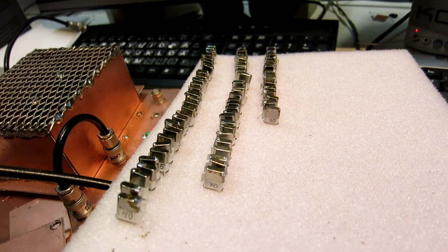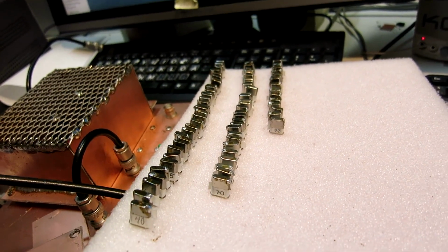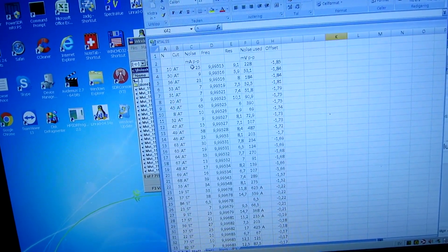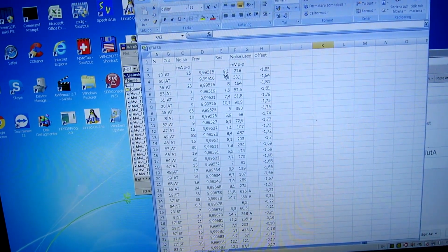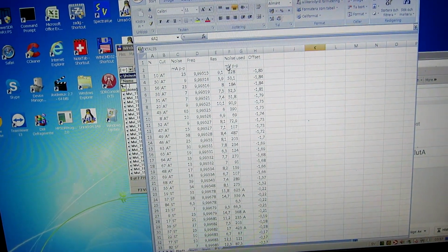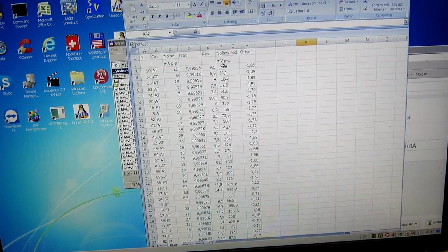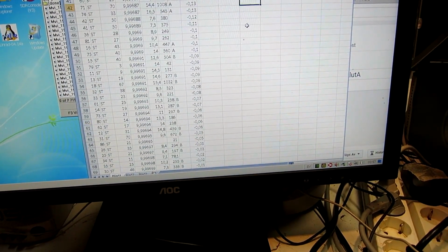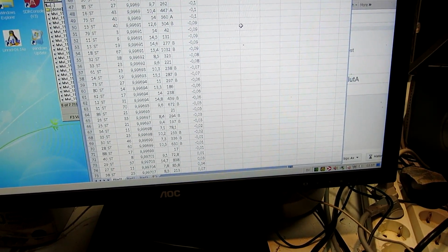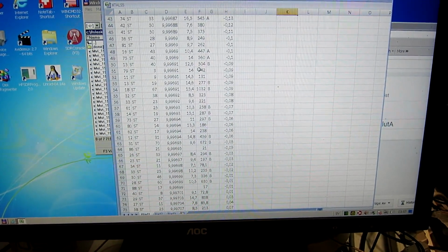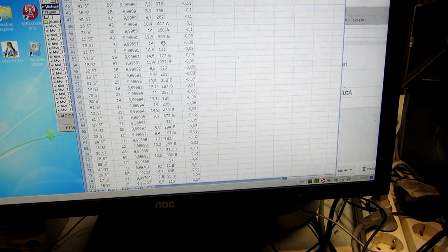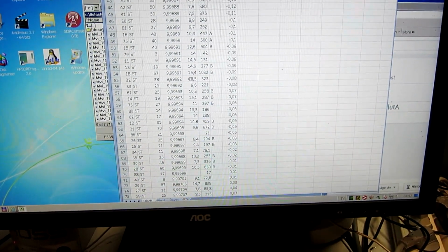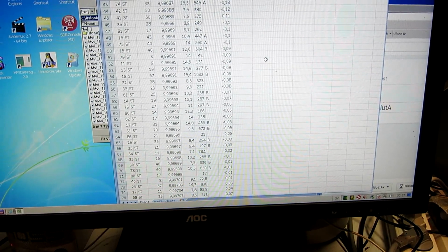These are all my 10 MHz crystals, recovered from various experiments. I have measured frequency, noise maximum current to avoid noise, and the resistance of them, and from that I can compute the voltage at which noise starts. And then I select from this table one group of 13 crystals here and another group of 13 crystals here. I don't want to use those that start to get a problem at a low voltage. This is this column. And I am not using either those that have a very low resistance. They will be valuable for some other purpose.